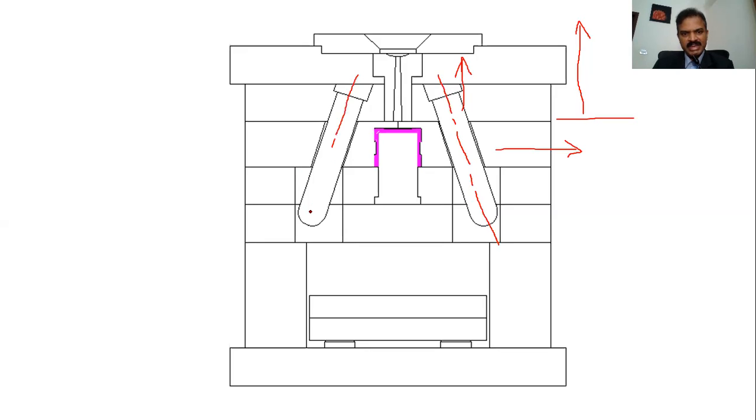And what should be this angle is a question. So basically the concept is the pin is mounted at an angle. Also it is engaging in the same angled hole in the split. When it moves up, it has no choice other than pushing the split to the side. Clear? Let's move to the next slide.